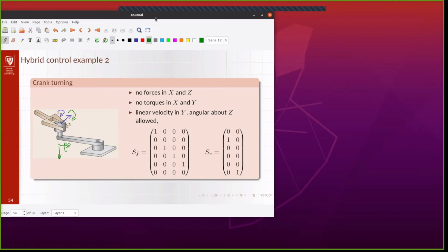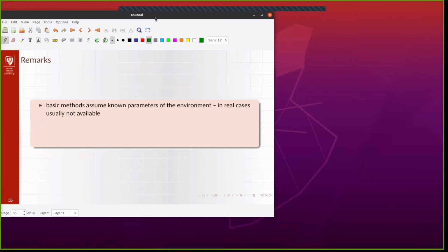So when you are approaching here in free space, the controller generates a big force like that. And when you come to the contact phase, when you got to the contact point, the controller starts to generate a force in the opposite direction to avoid applying too much force to the object.